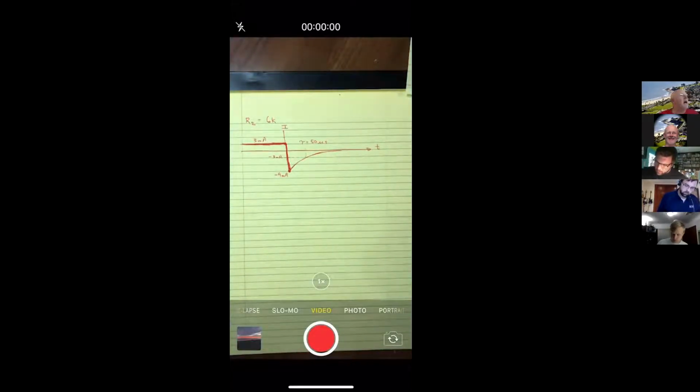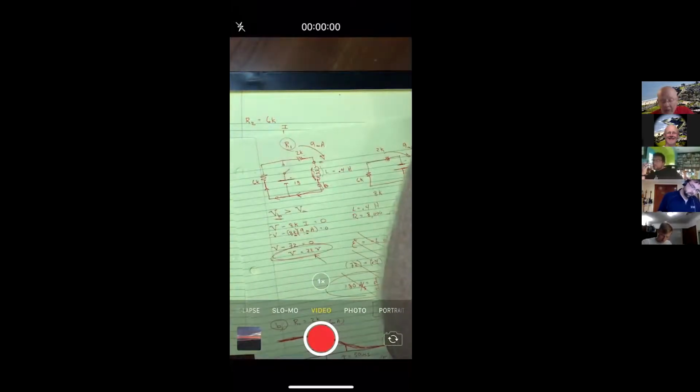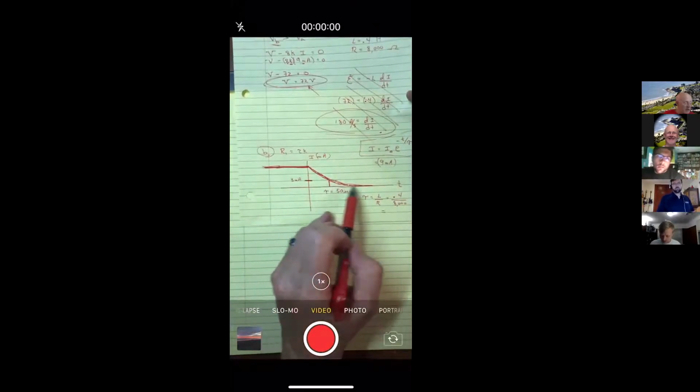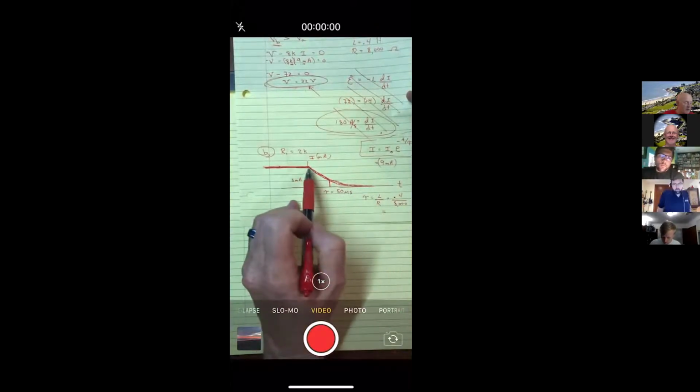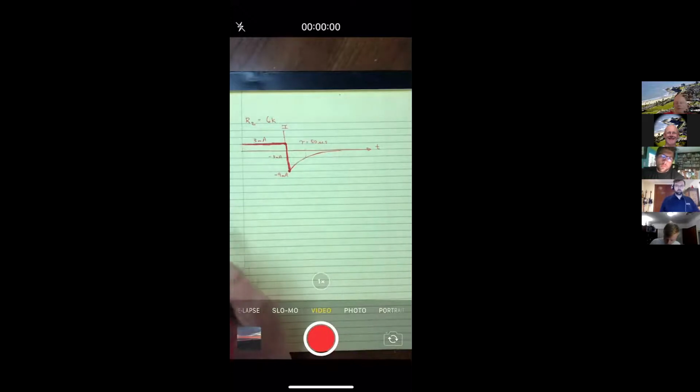But I think that's why the author made that very clear in the problem. Treats, make a freehand sketch. Yeah, treating the steady state directions as positive. Because I think he really wanted you to see that it would be a continuous function for the inductor, but a non-continuous function for the resistor. And the resistor is going to change directions before it decays away. So we've got a decay from the negative current on to 0.